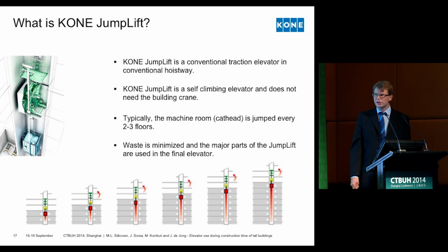And typically temporary machine room is jumping in 2-3 floor jumps. So it follows the construction of the building as it gets higher. And in the end, when this JumpLift is on the top, then most of its parts are or can be used by the final elevator, so that after all, the waste is minimized during the whole process.